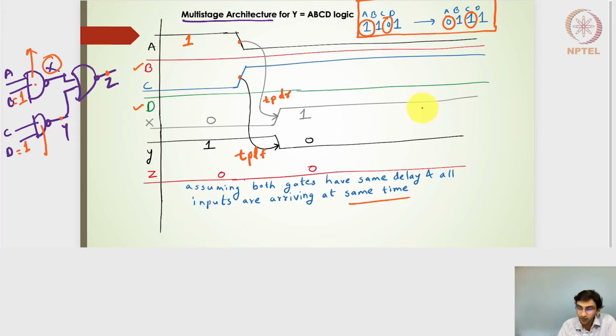So this particular alpha activity factor of X, accommodated with the capacitance at Cx, gives us the energy term C VDD square, and alpha Y Cy C VDD square. These are legitimate transitions, especially in this case, which arise because of the logical expression of this two input NAND gate. Both these expressions, one going high and one going low, have been achieved by the logical functionality of the two input NAND gate.